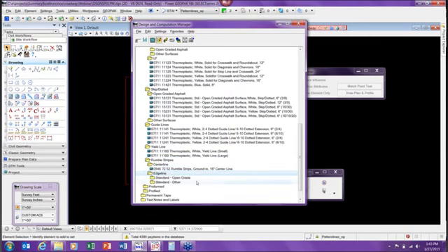Last but not least under here, and this is in thermoplastic and under paint, you have the rumble stripes, which is basically you've got two things going on here. You have a rumble strip for the center line, and all it's doing is drawing a line in the file for you for the center line computation for that rumble strip. And it is a construction element, so it does not plot.